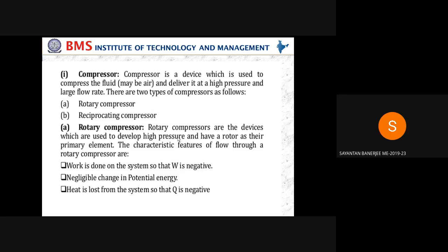So through that hole, we will see the air flowing at a very fast velocity, again due to the equation of continuity, right? So in such a scenario, is it okay for me to apply Bernoulli's principle? We have certain assumptions. It comes in fluid mechanics actually. If the flow is incompressible, but air is compressible, right? We cannot apply the Bernoulli's equation for compressible fluids because density varies from point to point.